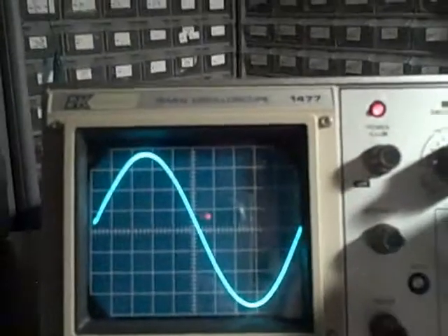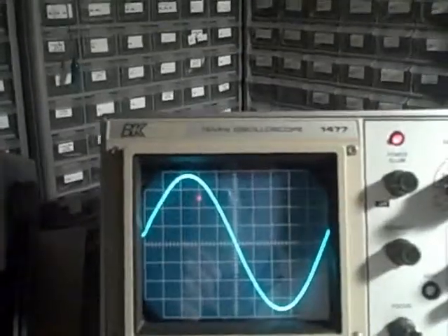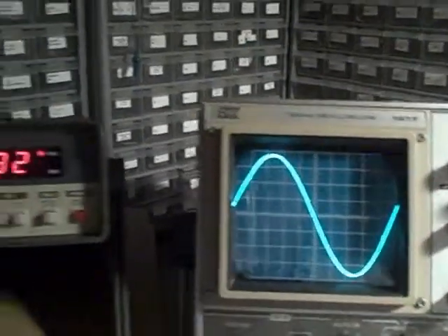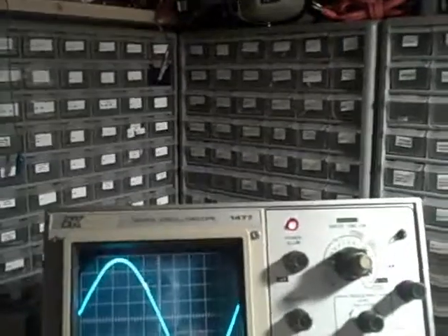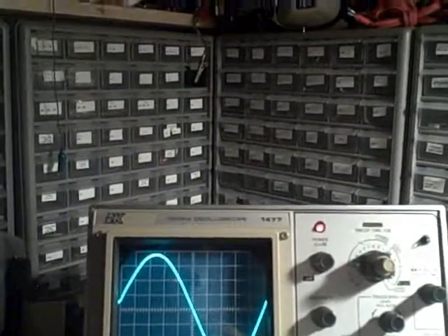Alright, 200 kilohertz, and no appreciable difference. 1 cycle on the screen, and essentially 1 cycle here too. Let's move the 0 a little bit. Okay. And we still are reading the full scale vertical 0.4, so we haven't begun to see any losses due to frequency yet. Okay, now we can't go any higher on our range, so now we have to start displaying more cycles on the screen.